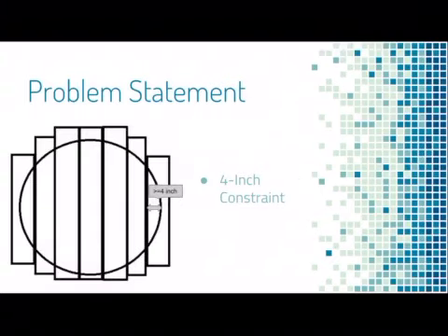Also, for safety reasons, we should make sure that after the flange is cut from the blank, the width from the tangent line that is parallel with the boards to the connection line for the first board from outside should be greater than or equal to 4 inches.